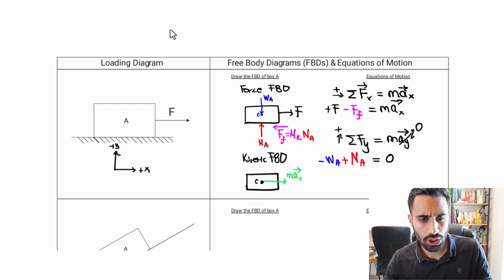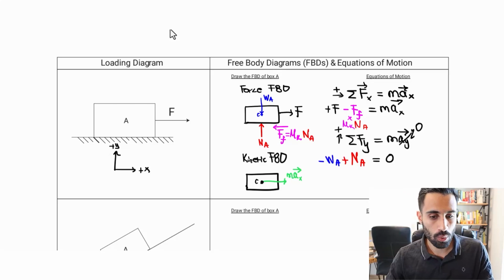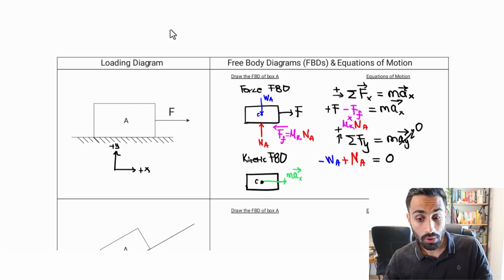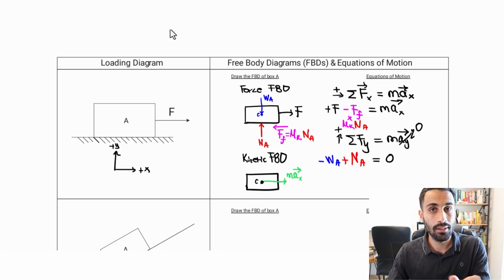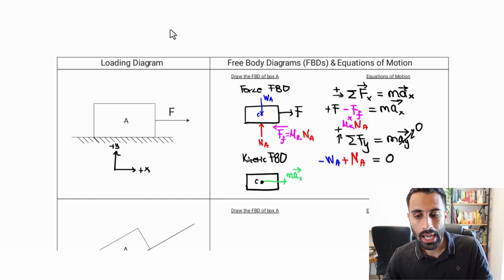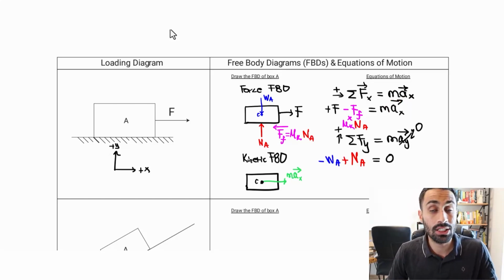And this force of friction, note, is going to be the mu kinetic times the normal force at A, as we broke down here. So we're going to start with this formula. That's typically the case for these. Start with the sum of the forces in the y. Find the NA, put that in there. The force here is likely going to be given, the force that's pushing to the right, producing the acceleration, then we can find the acceleration. It's a constant acceleration, it does not change with respect to time.